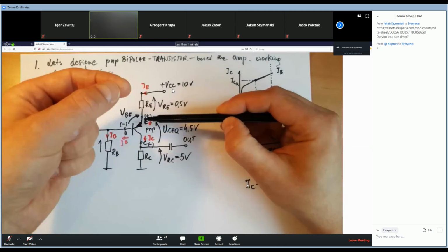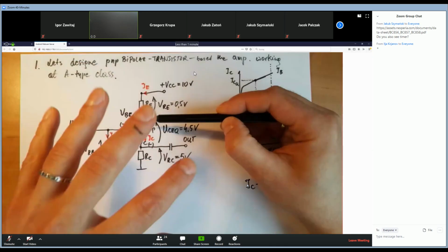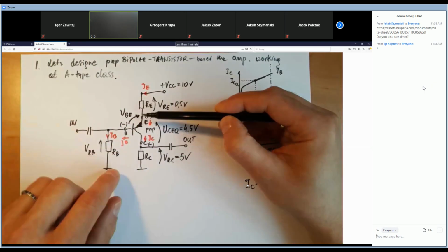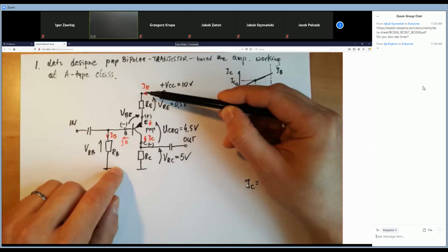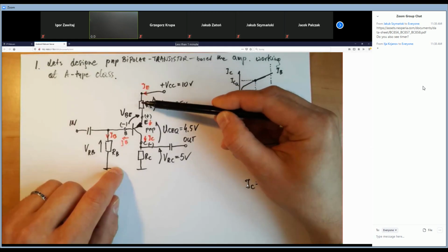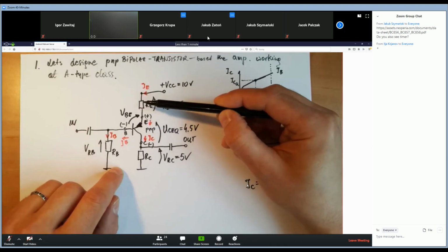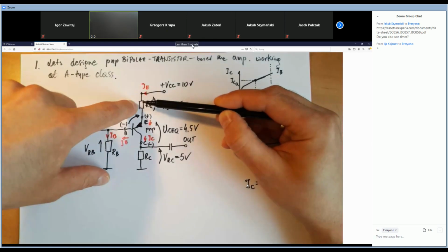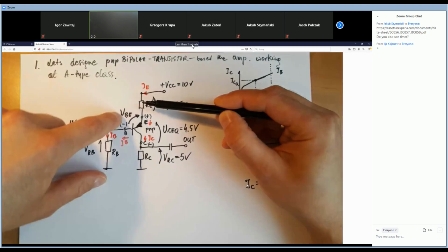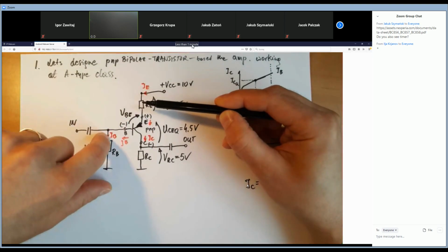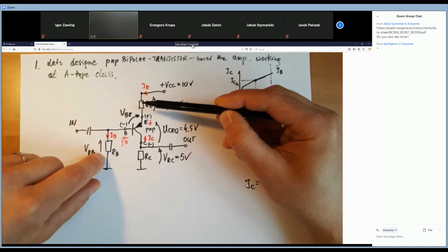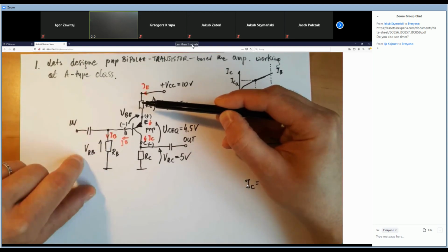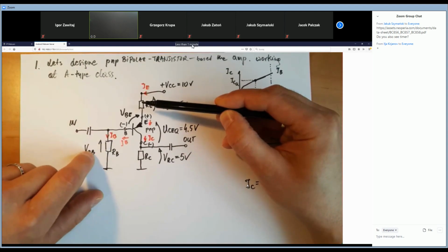So as you see, the temperature changes the resistance, and the current should go down in fact, because this resistance is increasing. However, due to the inverse feedback loop, the current, the beta is increasing because the voltage drop on it is going up.